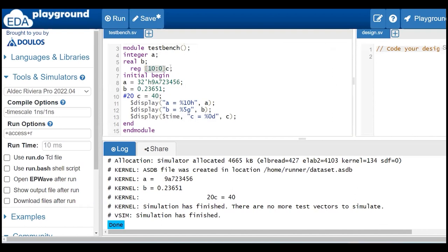Here in Verilog, we can call this a static array. Static array means at the declaration time only we take a fixed size value, right? But if you move to SystemVerilog, there we have static array, dynamic array, associative arrays. Dynamic array means if the size is not sufficient. Suppose we are facing this problem: initially we have taken a 4-bit size. If the size is not sufficient, we have to change it at the declaration time only. But in SystemVerilog, we no need to change like that. We can resize the array.